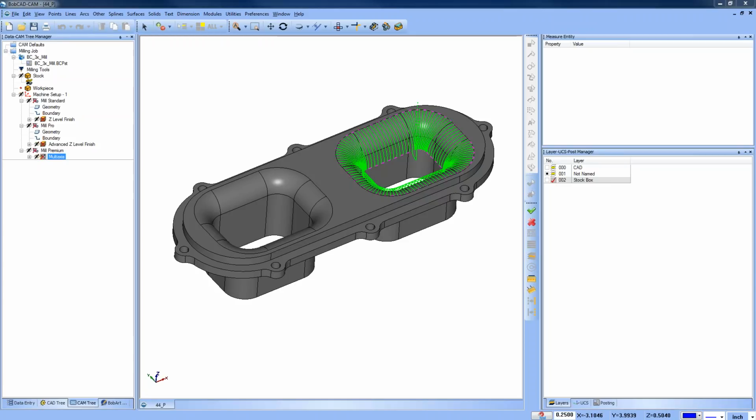Edward comes in with extending surfaces. That's a great point. It's always a good rule of thumb to start and finish off surfaces. You guys got no other questions there? Okay, here, Scott, unnecessary retracts. Great point. Keeping the tool in the cut so that it doesn't go up and down. Tom's got edge selection versus face selection. Great point. How do you select your geometry? Mike's got a question here. Getting the path that is optimal for the cutter. That might be cut direction. That may be how it starts. Lead in and lead out.